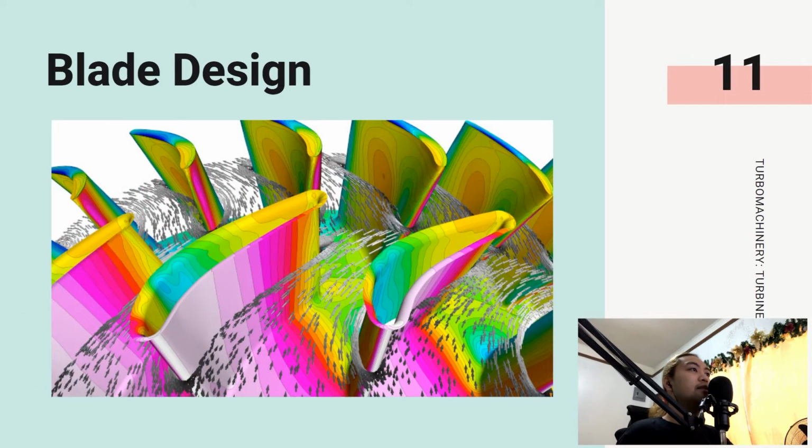Today's blade design is based on numerical methods and optimization, and is often used to improve the profile performance. These profiles do not follow a standard like the NACA profiles. The gas turbine technology is at such a high-end level that every blade is tailored for the specific application to give maximum performance. This, and the fact that blade profiles are a trade secret of the manufacturers, prevents standardization of modern blade profiles.